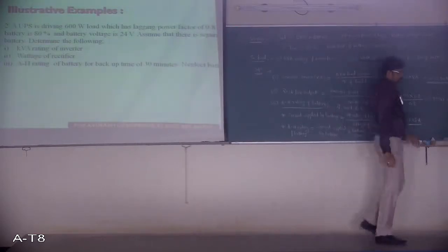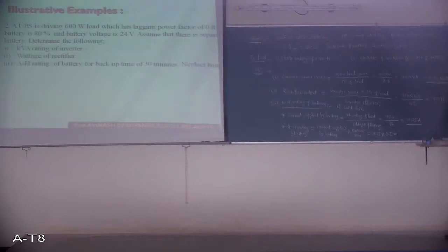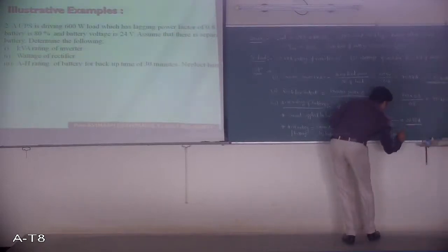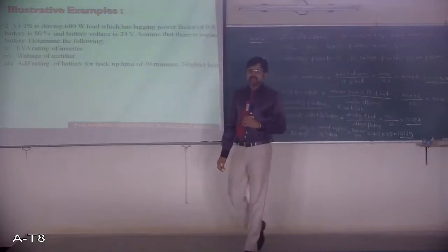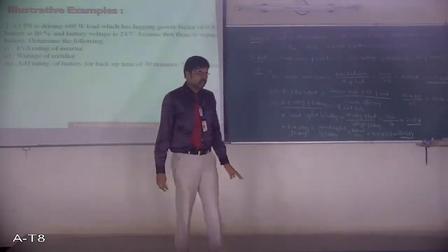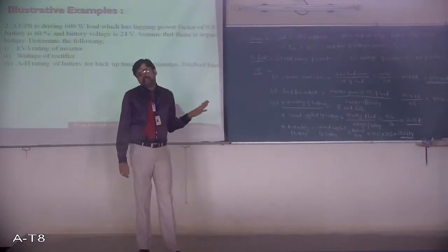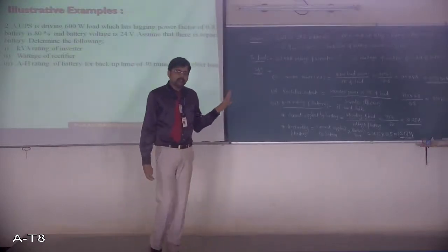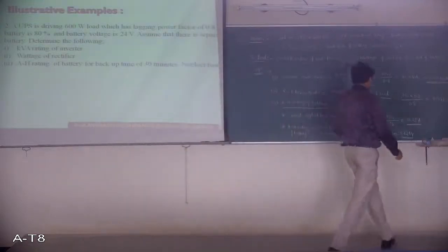See what you will get. 31.25 into 0.5. How much is that? 15.625. 15.62 ampere hours. Approximately 16 ampere hours is the battery rating required. Okay, is that clear or any doubt here? Please let me know. Very simple it is.